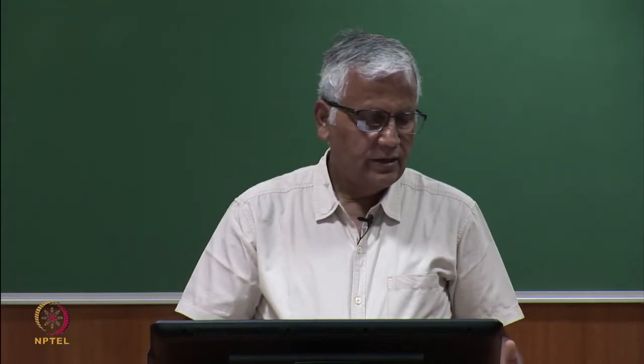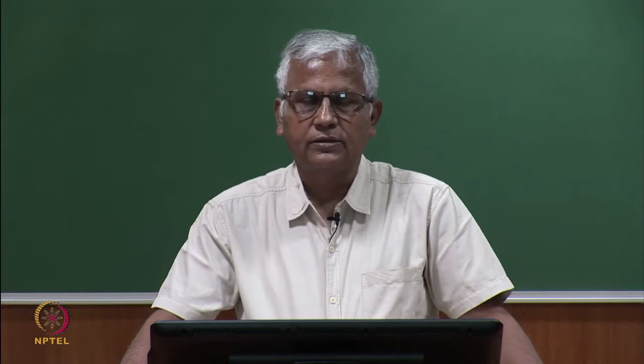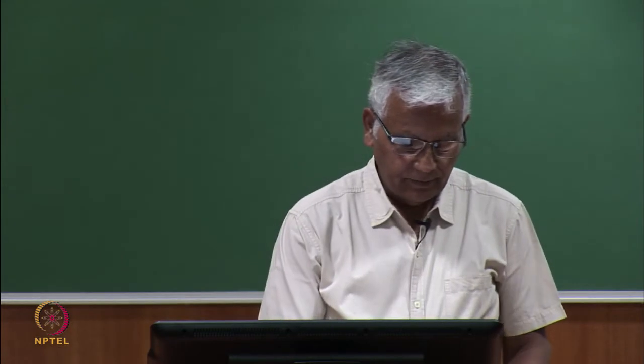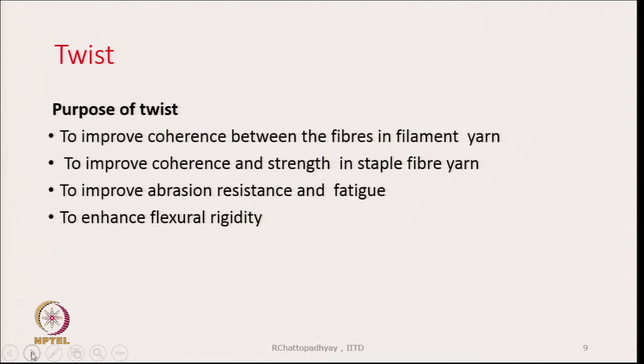The other aspect is fatigue resistance. There are many occasions where the yarns will be subjected to cyclic extensions, and there fatigue sets in and the yarn finally fails. So, we need to improve the fatigue resistance, and twist has a very important role there. Twist can also influence flexural rigidity, that is, the bending rigidity of the yarn.